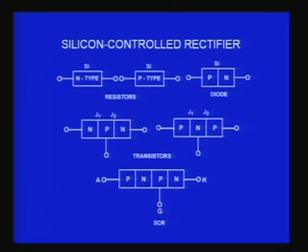If I have a simple N-type silicon semiconductor, then it becomes something like a resistor. Depending upon the doping, the conductivity will change, and therefore the resistance. So you can have either an N-type resistor or a P-type resistor depending upon what you dope with. When you combine the two types in the same wafer, you can have a junction diode. This we have discussed at the earlier stage.